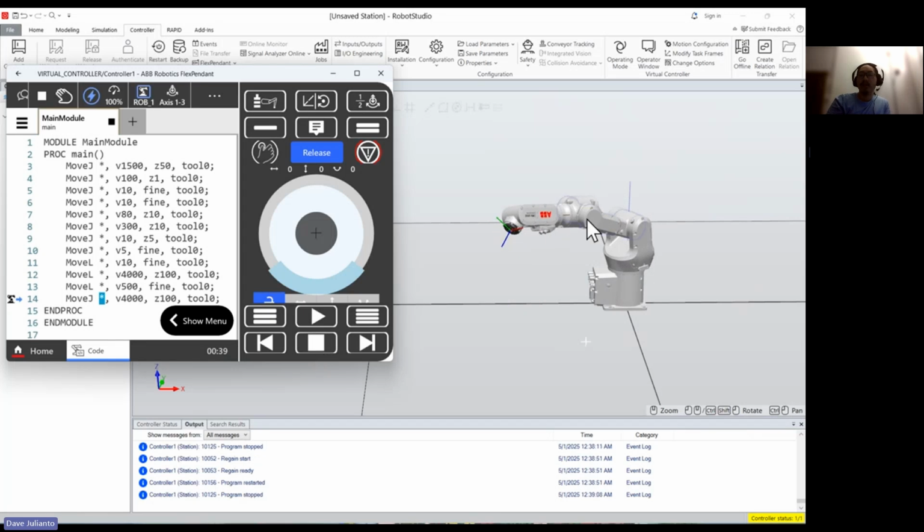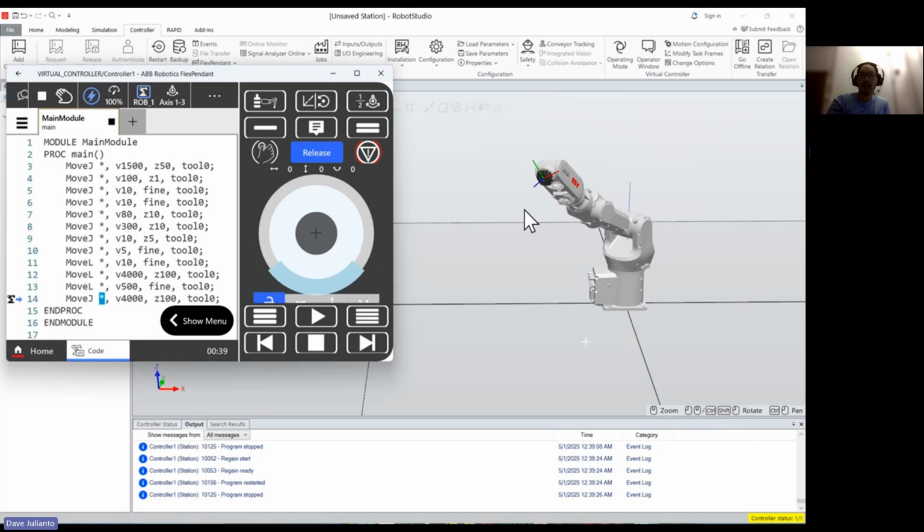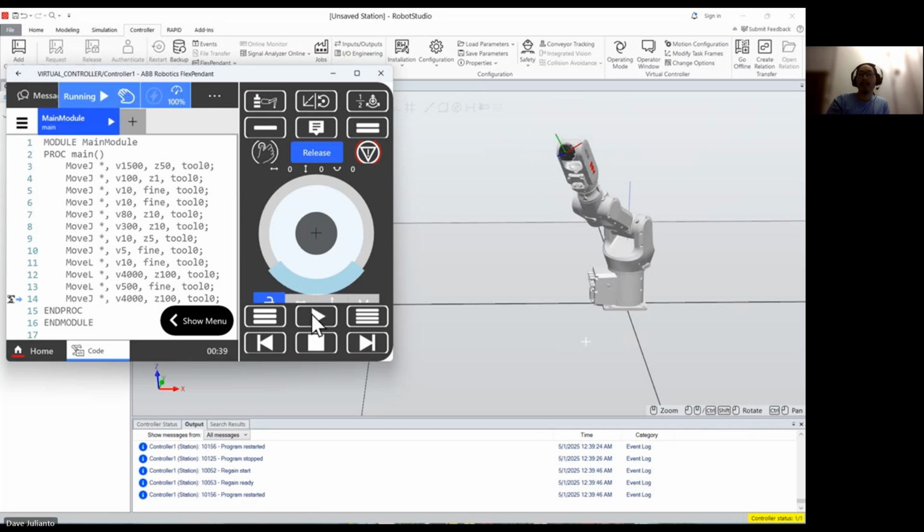Then we try to use move J to bring the robot back up closer to the starting point with a pretty fast movement. But soon after it reached the defined point that we jogged manually here, it will return to the original starting point and also adjust its speed and accuracy of positioning. So it will come back up.